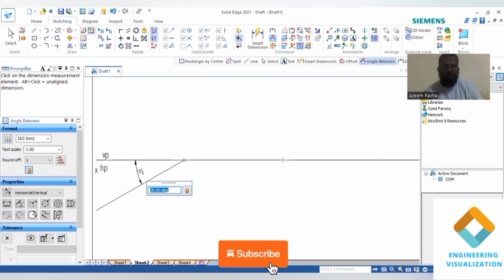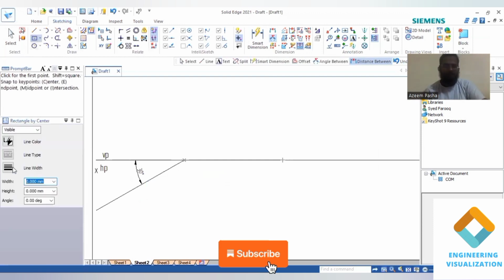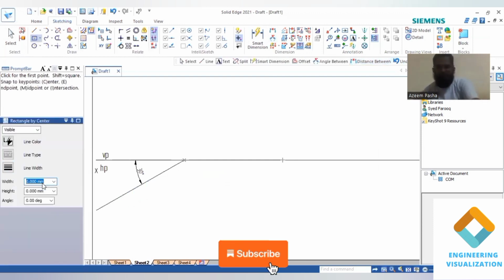Now you have to take the square of dimension 40, and then we have to place it with respect to that vertical edge. You can give the width and height the same, using the rectangle by center command, width 40 and height also 40. The angle you can give is 45 degrees, so that it is easy for us.